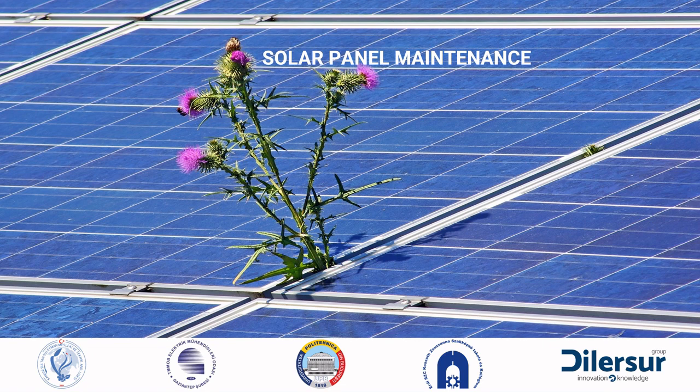The critical activities that must be conducted during visual inspection of solar panels are as follows. Inspection of solar panels mounting. Inspection of solar panels integrity, checking for moisture condensation within the solar panels, corrosion of contacts, delamination of cells, cracks on the cells.